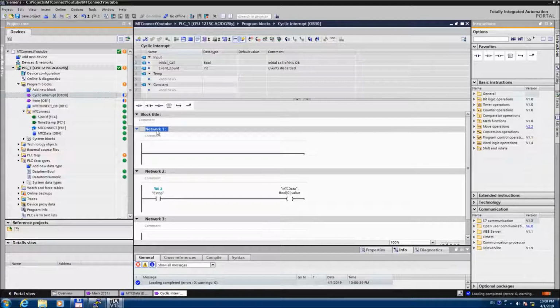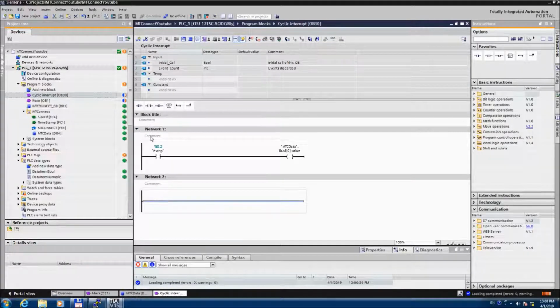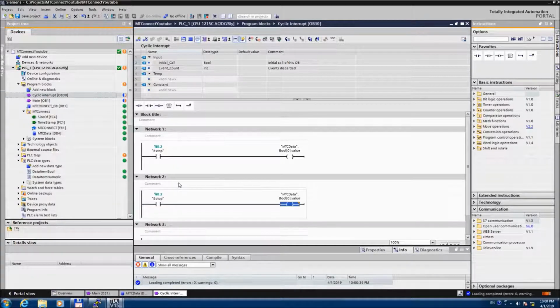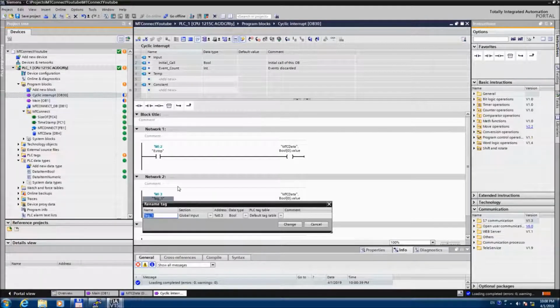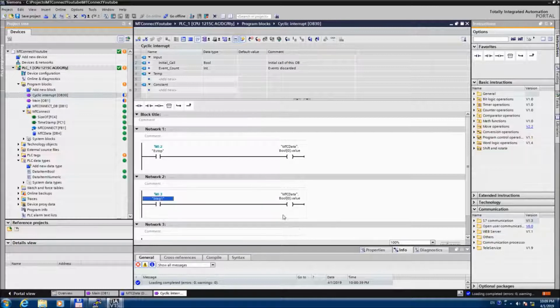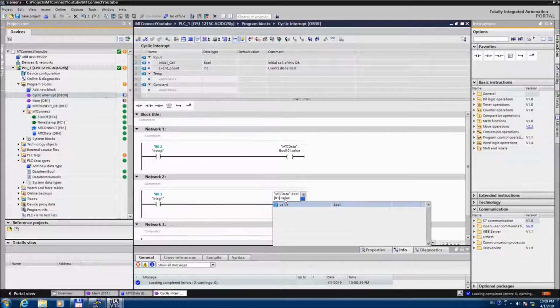We will continue connecting up data, so we'll probably have, let's say we have one more digital, so I 0.3, next physical input. We're going to rename that tag to, I believe it was B tag 1, which was the next tag, and that was Boolean. That'll be part of Boolean 1.